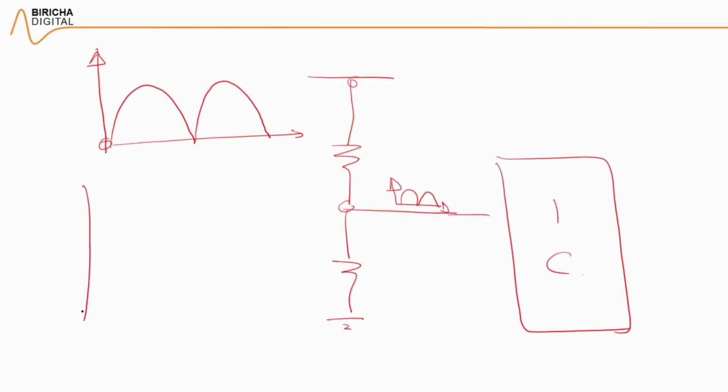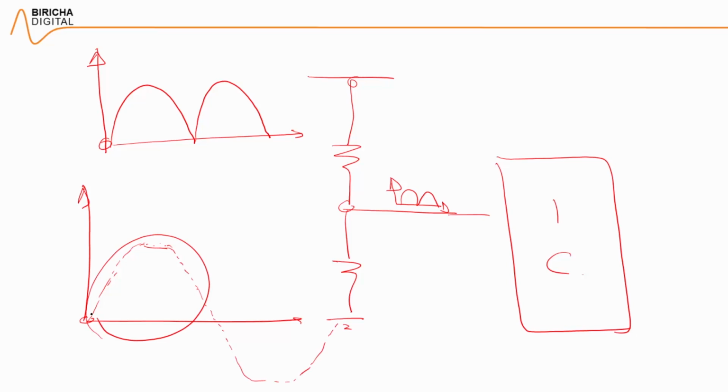The problem is that line voltage is rarely sinusoidal. If you actually look at line voltage in many countries, the power quality is so poor that the line voltage in fact looks something like this. This shape is very common. This sort of semi-triangular with a crop top is actually very common when you look at the actual power sinusoid that comes out of a power socket.